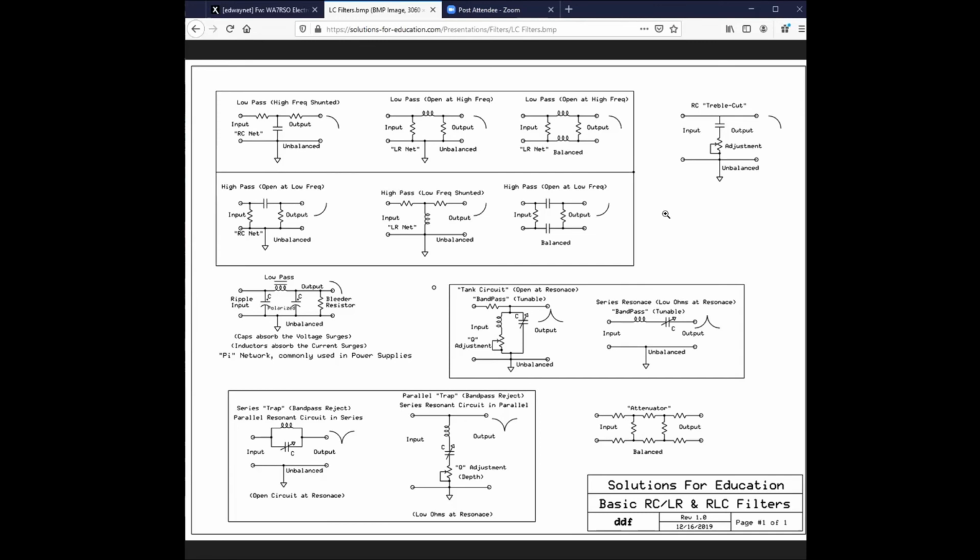In terms of how much inductance, I frankly don't know. It's way down in the low microhenries. Way tiny. Now there is one other thing, and that is as you coil the wire, each coil has an effect on all other coils. So you have mutual inductance, and as you add coils, the factor goes up quickly. Hence the formula for inductance that you'll find in the ARRL handbook as an example. By the way, if you ever want to get into a discussion on transformers, there's more there than meets the eye as well.